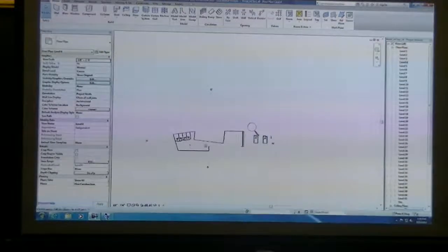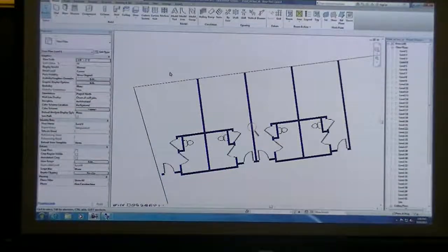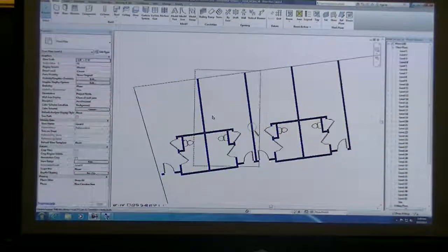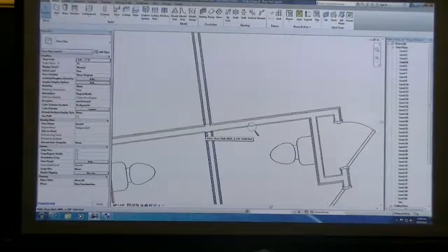And if I look at all of my wall types, because I've placed them, I automatically have a presentation floor plan that I can present in studio and print out. In AutoCAD, you'd have to go back through and draw a hatch and trace all your walls and do a solid fill. As long as you have all your different wall types set up, at any moment you can change your view and look at the different details of your wall. It's really all I can go over today at the moment.